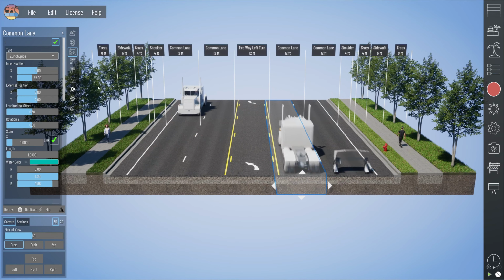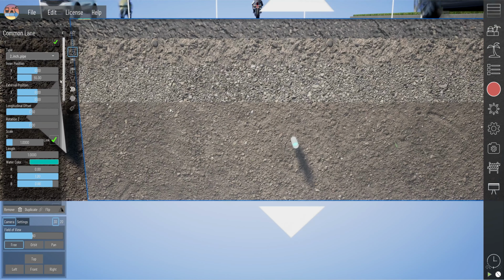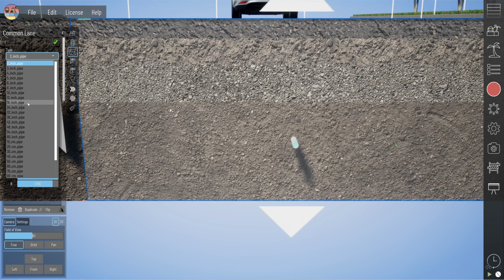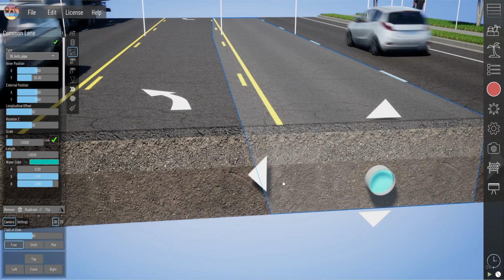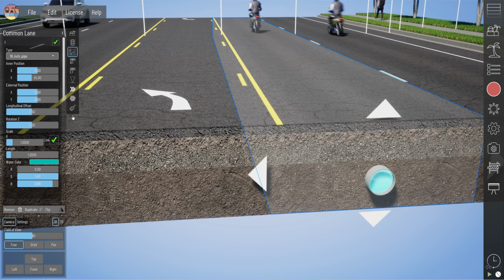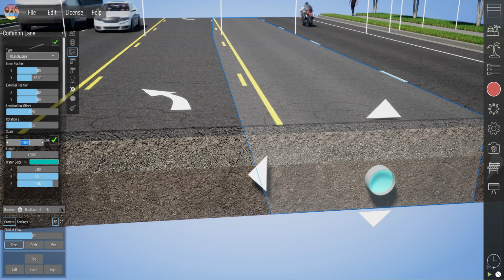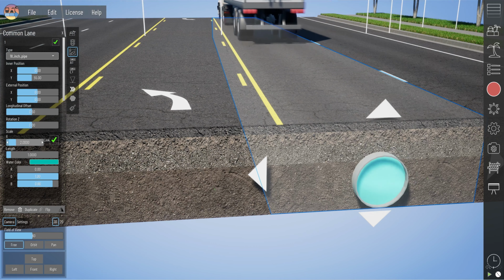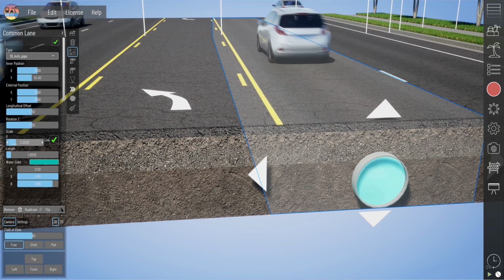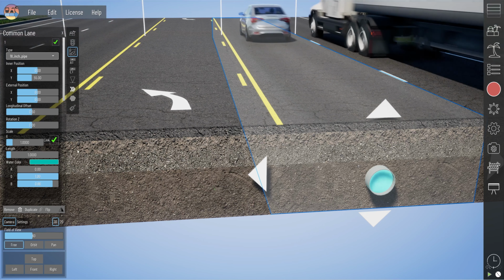If you look really close, you can see here we now have this 2-inch pipe. We're going to change that to an 18-inch. You can do metric sizes. And then from there, you can even do scaling, and you can link the scaling as well. So if we wanted to do 18 inches times 2, we can do that. Now we have a 36-inch pipe. So lots of options for adjusting and scaling underground utilities.